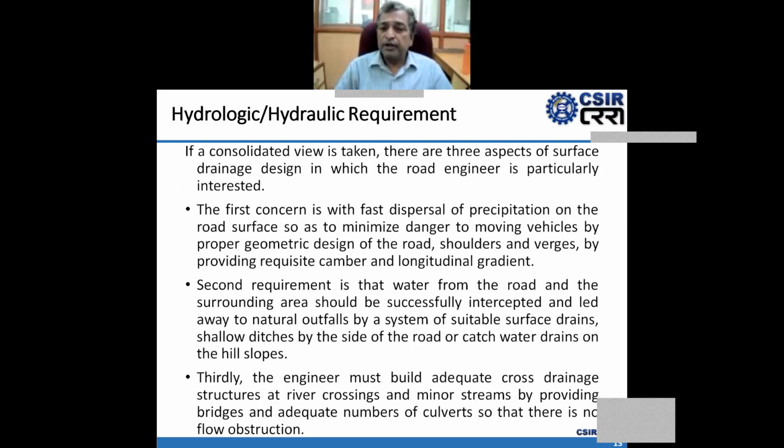If a consolidated view is taken, there are three aspects of surface drainage design in which the road engineers should be particularly interested. The first concern is the fast dispersal of precipitation, rainfall on the road surface so as to minimize danger to moving vehicles by proper geometric design of the road, shoulders and verges by providing requisite camber and longitudinal gradient.